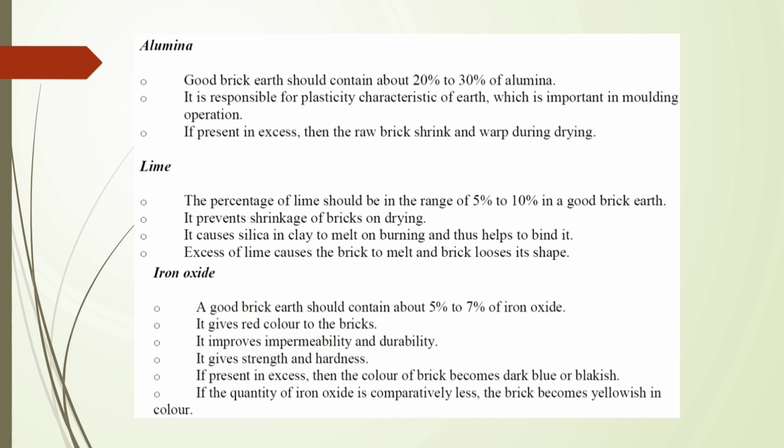The sand alone is infusible, but it slightly fuses at kiln temperature in the presence of lime. Such fused sand acts as a hard cementing material for brick particles. The excess of lime causes the brick to melt and hence its shape is lost.